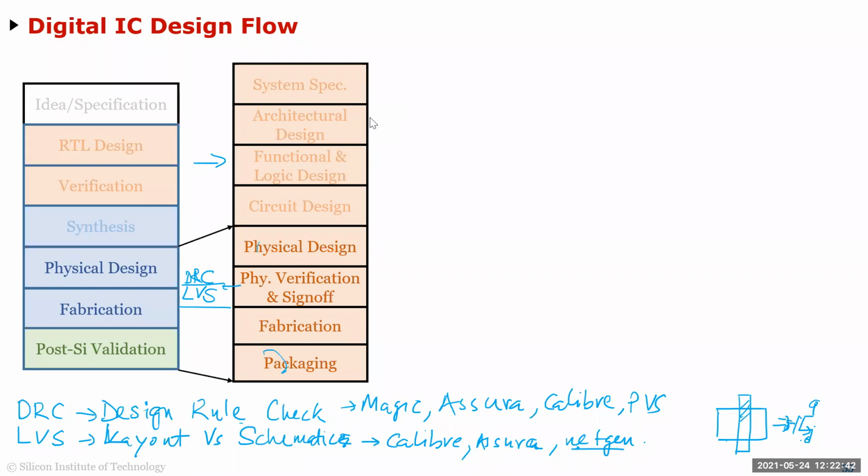So the answer is not that one is more accurate and one is less accurate. Given a certain complexity, you just can't do it full custom, because it will take you, like an Intel chip, you could do it full custom, but you'd probably be taping out a chip every 50 years instead of every year. So that has to be done semi-custom or fully automatic. Whereas if you're doing a power amplifier or LNA, low noise amplifier, you just can't do semi-custom. It's just two devices and it's all manual. Okay, I hope it answered your question, Satya. If you didn't, just raise your hand.